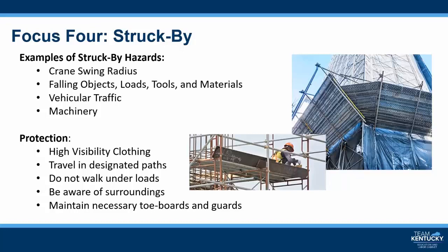If a worker is on a lower level and there is potential for materials or tools to fall from an upper level, then a toe board or some other means to prevent the materials from falling, such as securing materials or tools, is required. Another struck-by hazard involving cranes is falling loads. Workers should never stand or work under a load on a crane or other hoisted materials.